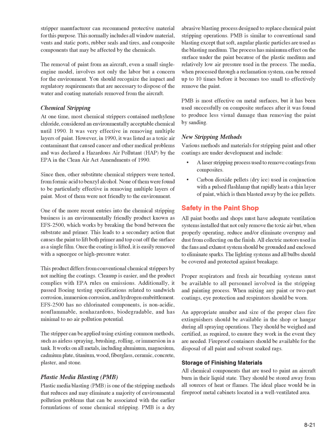Proper respirators and fresh air breathing systems must be available to all personnel involved in the stripping and painting process. When mixing any paint or two-part coatings, a protective respirator should be worn. An appropriate number and size of the proper class fire extinguishers should be available in the shop or hangar during all spraying operations. They should be weighed and certified, as required, to ensure they work in the event they are needed. Fireproof containers should be available for the disposal of all paint and solvent-soaked rags.